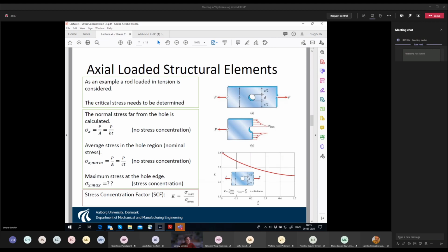And of course, you cannot do the experiments for this sort of hole made by a needle. But if you have some sort of recognizable hole so that you can do the measurements, then it's quite amazing how accurate this prediction is. So then if you are somewhere here, then you are able to put some tensometer here to measure the stress, and then you compare the stress with the theoretical prediction, and it perfectly matches. So that's all fine.